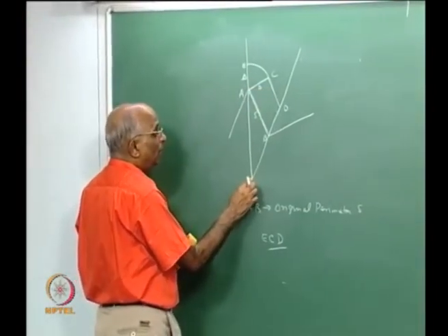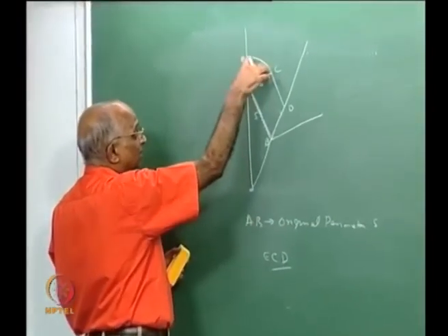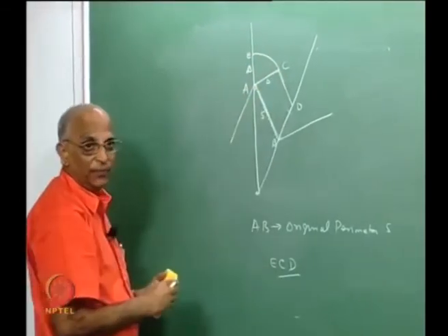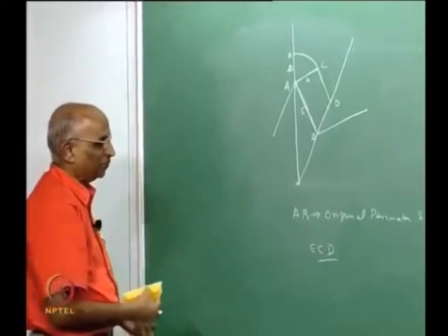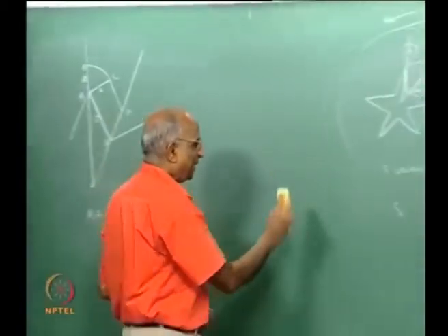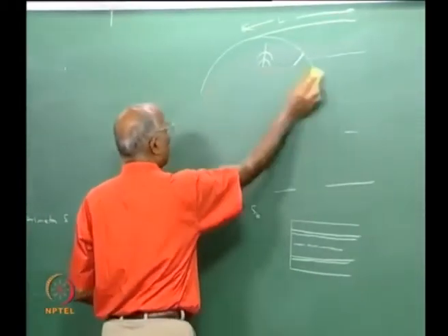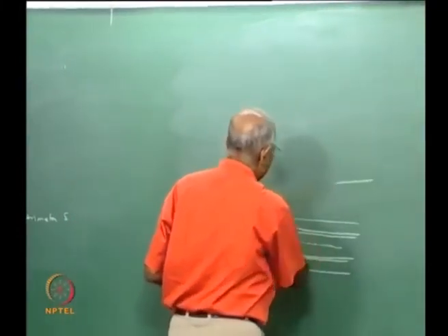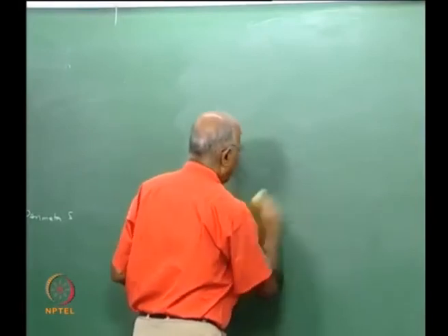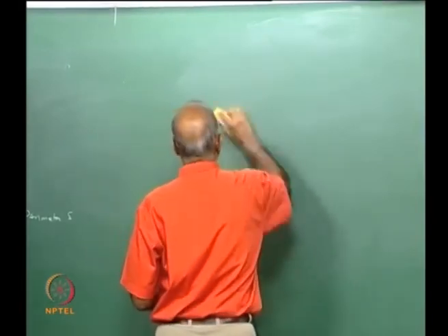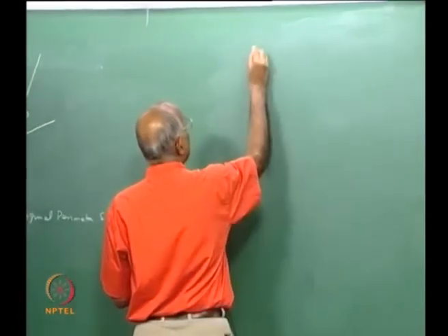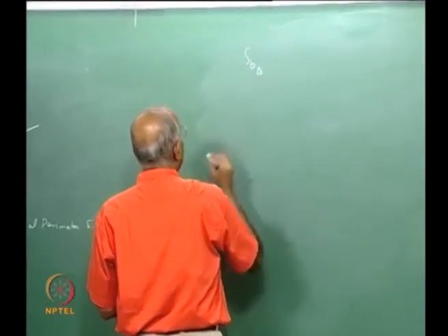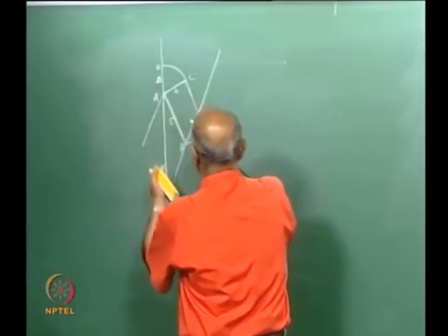I would like to know what is the value of EC when this line has progressed by a distance delta. Now you can tell me. As I keep telling, the progression of a surface is all what matters. It is a geometric problem, there is no combustion, there is nothing. All what we need to know is what is the value of the new burning surface area when the burning at the surface has progressed by a distance delta over here.